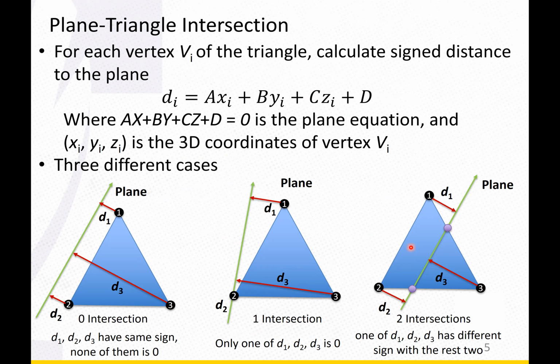And another fundamental problem for this method is if the mesh has very bad triangulation, meaning it has problems, like some self-intersection, right? Two triangles fold into each other, or there is some incorrect topology. Let's say, one edge linked to three triangles, which is undesired for a CAD model, for a solid model.